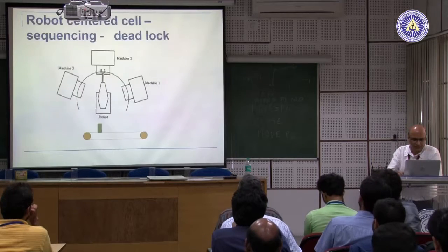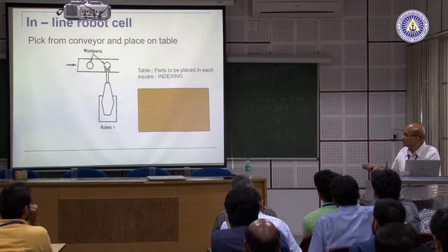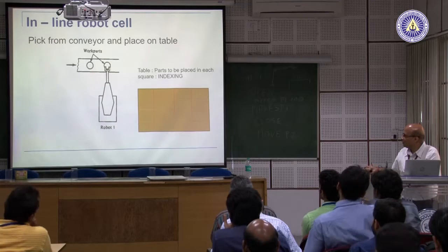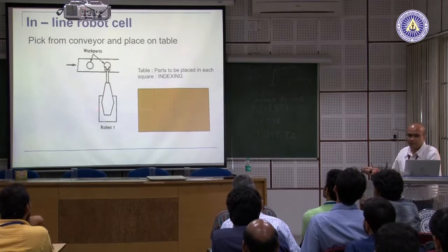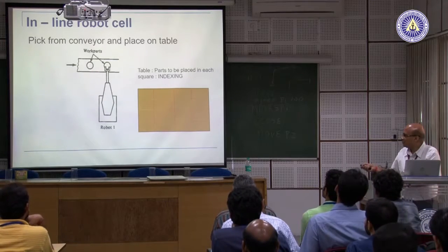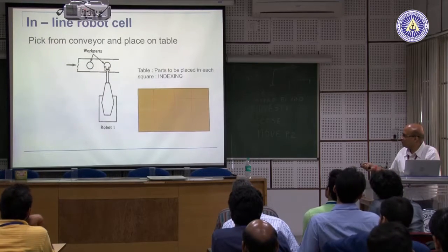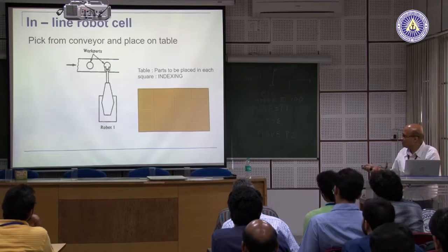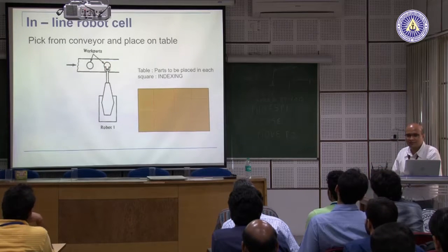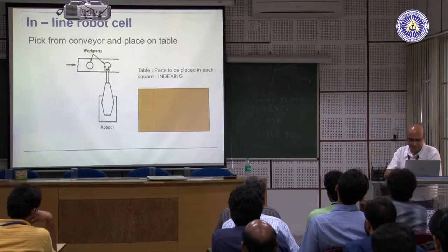Say for example, in this particular case, the conveyor channel 1 can communicate with robot channel 1, okay. As soon as the part comes, it will make the channel high, okay, and the conveyor will stop, the robot will go and pick up. The moment the robot picks up, it will make that channel low. So, now the conveyor understands the part is gone, it will start again, okay. So, simply by on off kind of sensors, machines can also communicate.